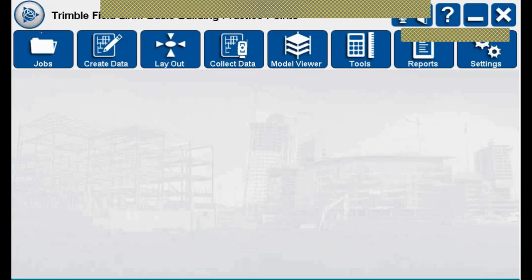But the key is you need to go to DDUNITS and make sure that it is set to unitless as opposed to, I believe the default in CAD is inches, and that depends on how you set up your AutoCAD software. But DDUNITS is the name of that command. Let me see if I can type it in. But if we decide not to do that, you just scale it down by a 12th at 000 again.